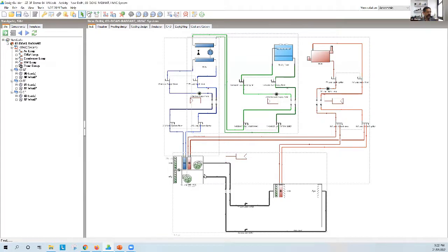The only thing that's sort of non-traditional about it is that you always have more than one air handler. If I was going to do this in detail, I'd probably divide the floor plate up into north, east, west, south, and the center zone, and then I'd probably have air handlers which did each orientation and one which did the internal zone. But for the present, this is a pretty good system. Now, this is all pre-connected, so you don't have to do very much indeed. But if you want to connect anything, let's do one thing. I'll add another AHU, and I'll add another zone group, and I'll show you how we do that. We'll keep all the east zones on one air handler, and all the west zones on the other air handler.